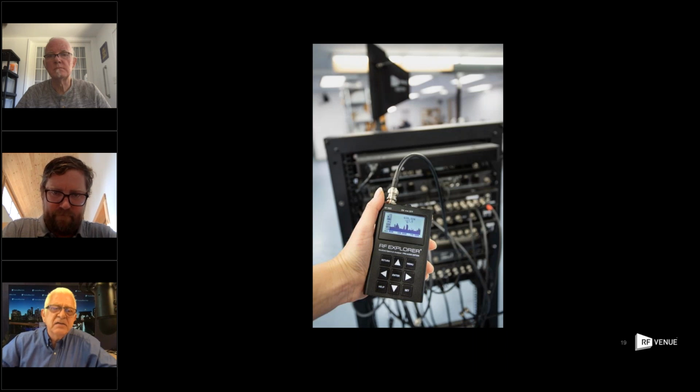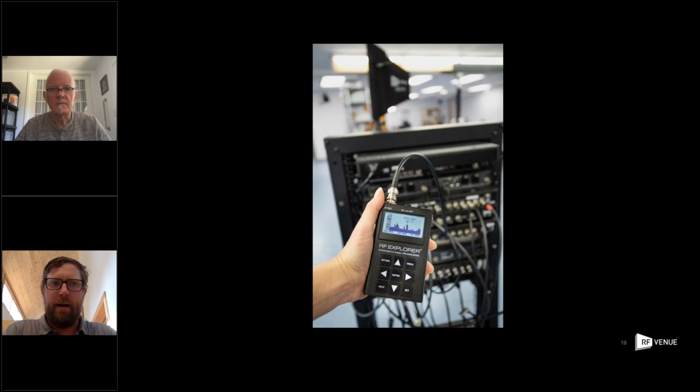Does your pad/amp setting remain from the last time you set it, or does it default to the pad when you start up? It remains from the last setting. Out of the box, it defaults to 0. And those settings are recalled. So really, if you're playing around with the LNA or the attenuator sections, that's not something you're going to want to hold from show to show. And that's what's so good about having the presets.